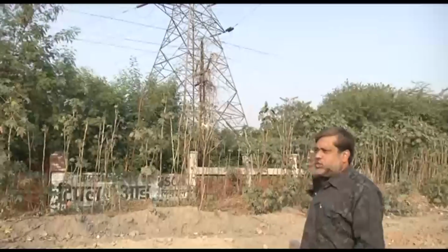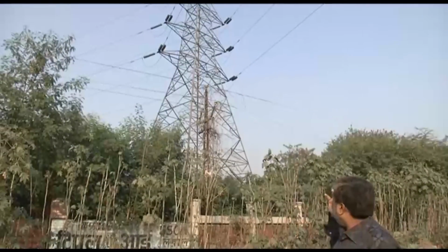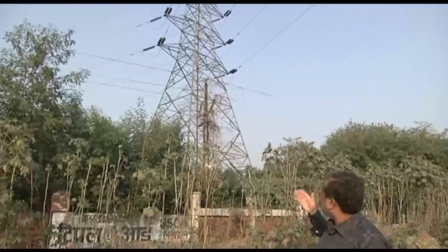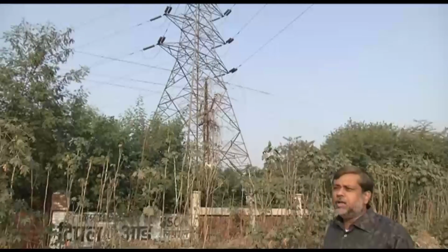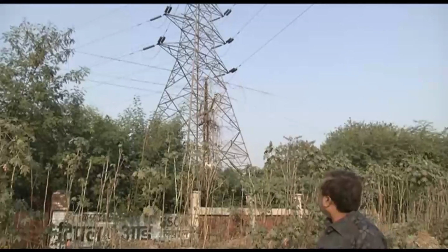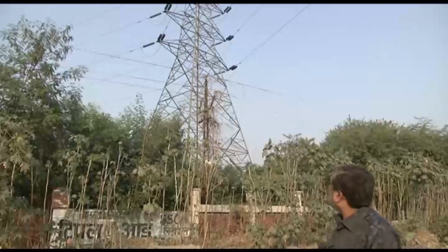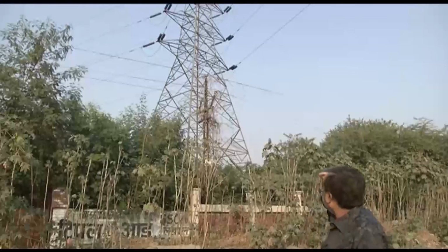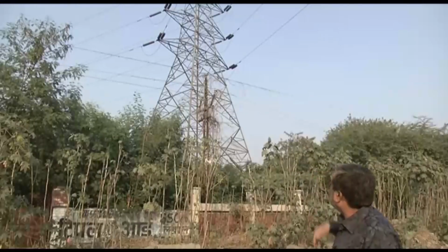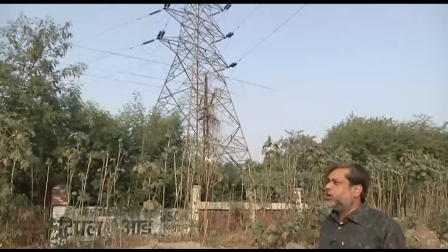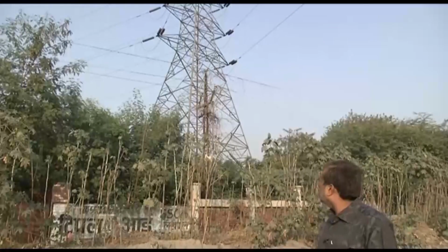The way this Stockbridge damper helps to control the vibration is whenever there is a vortex induced vibration that comes into these wires, which happens in a pretty big frequency range from about 5 Hz to 150 Hz, then this vortex induced vibration creates a huge change of amplitude in the wires, and it can actually destroy the wire, it can create a huge power problem.